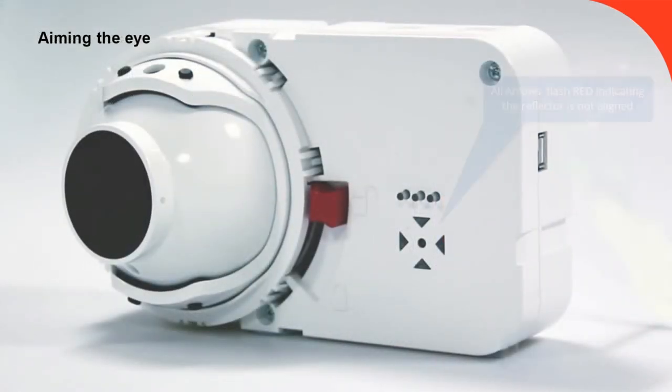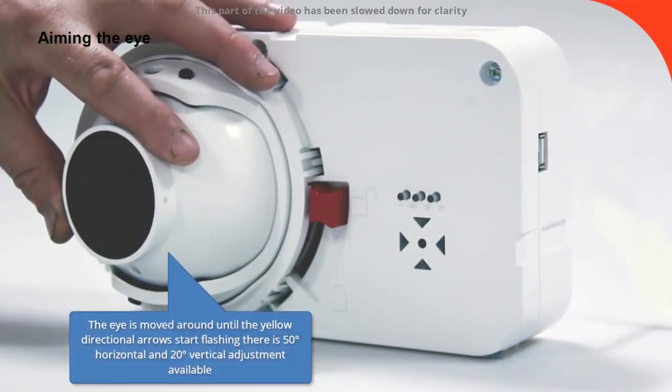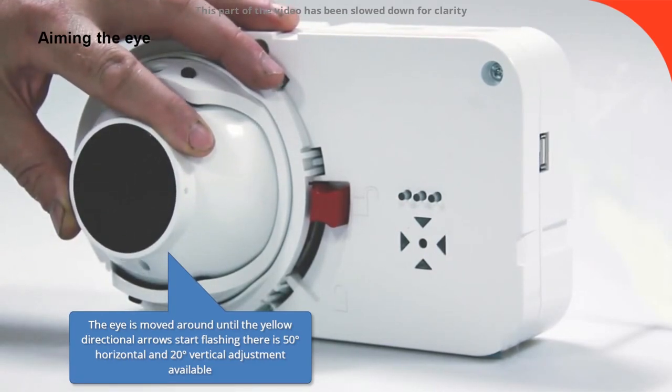The alignment procedure is child's play. Once unlocked and powered up, the eye can be roughly aimed at the reflector. The yellow arrows will quickly start to flash to indicate the required direction of movement to achieve full alignment. Once all of the arrows flash green, the lock button can be applied.